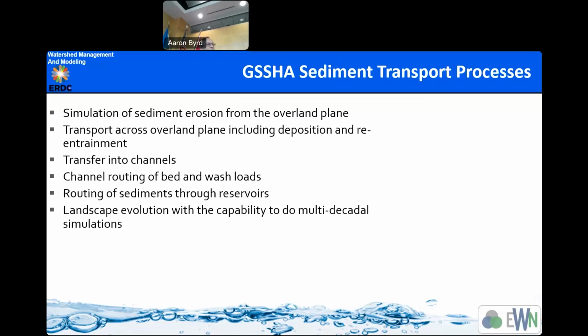One is rainfall impact, and the next is the velocity, all that energy of the hydrology itself, and that is the shear stress, right? So if the shear stress is higher than the critical shear stress, then there is erosion, and the particle which is attached gets detached from the original mass and then is a source of sediment at that point.